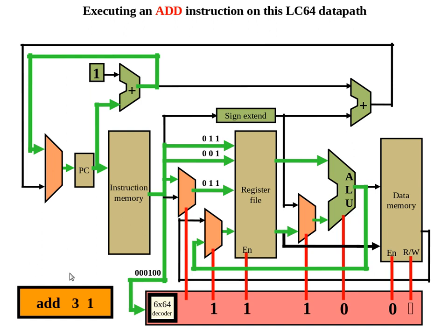Up here, add does not mess with the program counter, so we're going to add 1 to PC and make the program counter go to the next value. The program counter signifies the address inside of memory, so by adding 1 to the program counter, we are signifying to go to the next instruction that is inside of memory. All right, I'm going to stop here because we just went from probably the finite state machine, which sounded great, to what's going on. How are we doing?